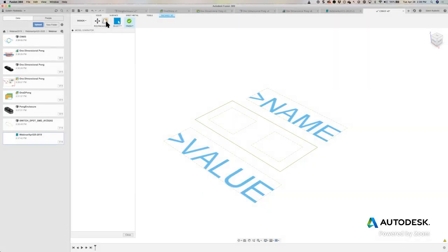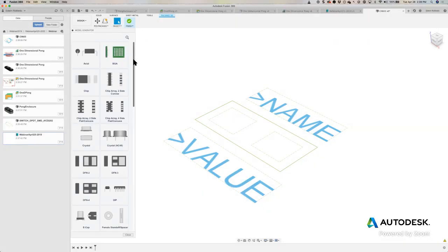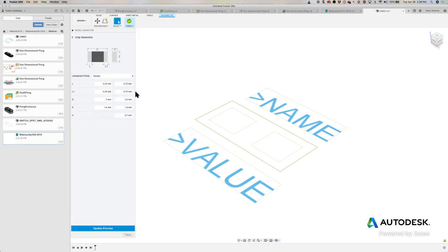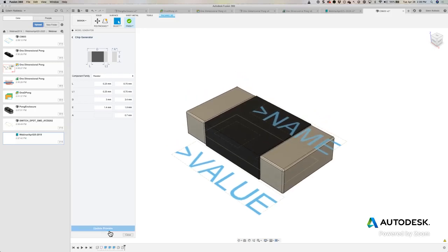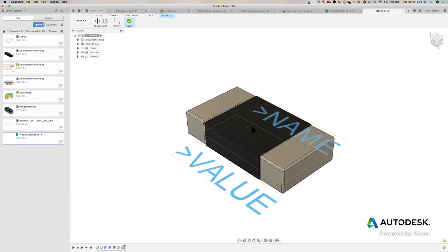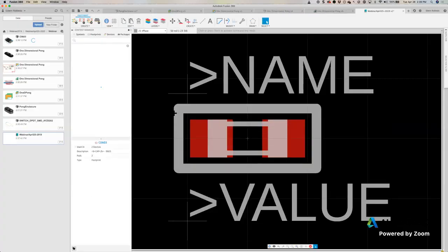And then right here, I could invoke the template and select resistor, then just put in the dimensions here, and then I could assign a 3D model to it. Actually, it's a little too big, but for the sake of speed, I just wanted to make it really quick. Click finish. Okay, now this component has a 3D model assigned to it in Fusion 360. So now if I start using this library or this component in Fusion, in my schematic and on my board, when I go to 3D PCB, these resistors will actually be mapped out with the 3D model.